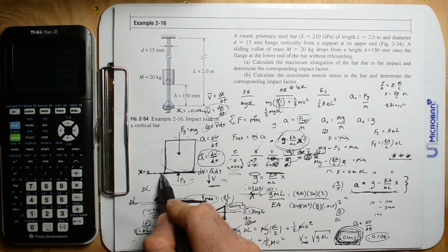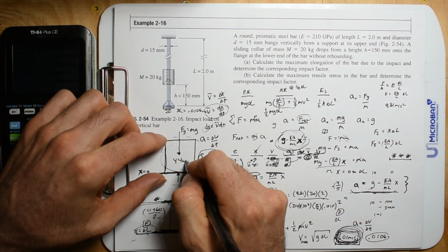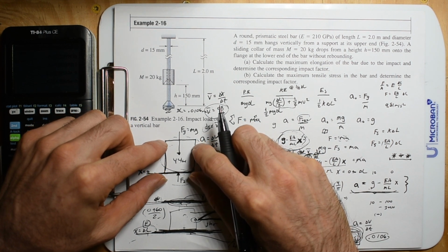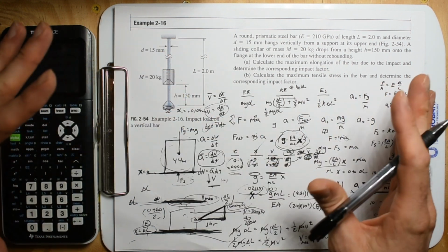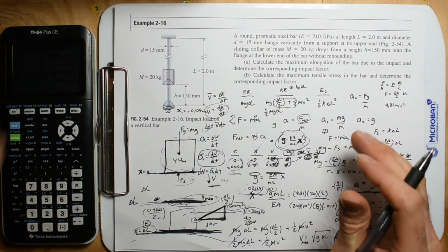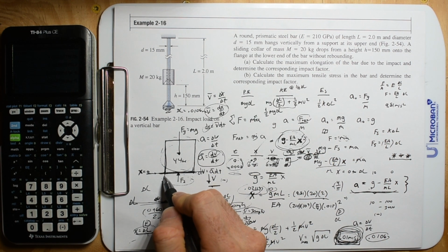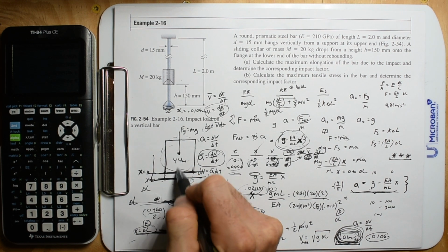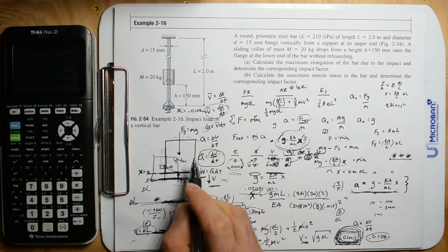So this is the least amount of, and it's not the least amount of impact. I mean, if this weighs 44 pounds, you don't have to hover it. You could have 22 pounds on it, and then you're holding 22 pounds, and then you could instantly let that go. And that would be the same problem: you'd have to say at 22 pounds, what's your initial change in length there, set that datum equal to 0, and then you could do the problem like you're just impacting it with 22 pounds of force.